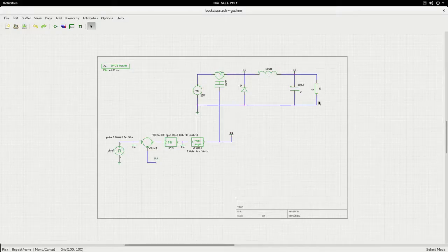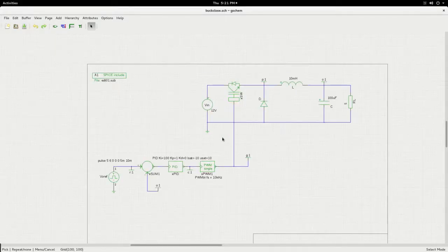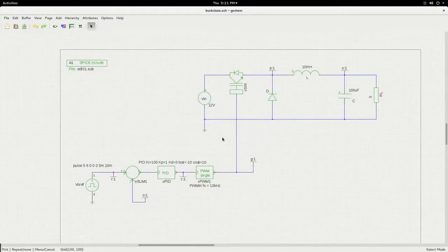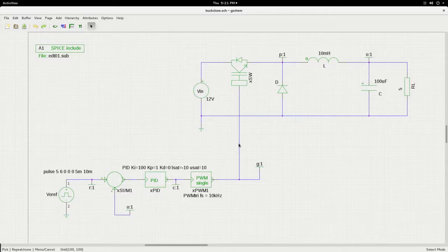You can use the same approach for any other converter too. Let me zoom in. So you must be able to recognize this portion. You see that this is a DC source, 12 volts. This is the switch, power switch, which we will be controlling through some duty cycle, and you have the buck converter portion, L and the C, which we used in the open loop simulation, and the inductor will freewheel when the switch is off, when the switch is on, inductor will charge.